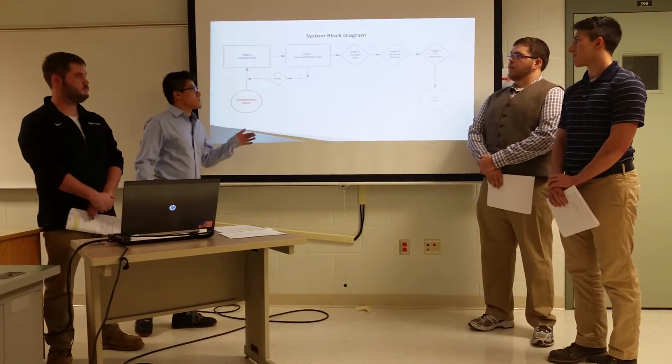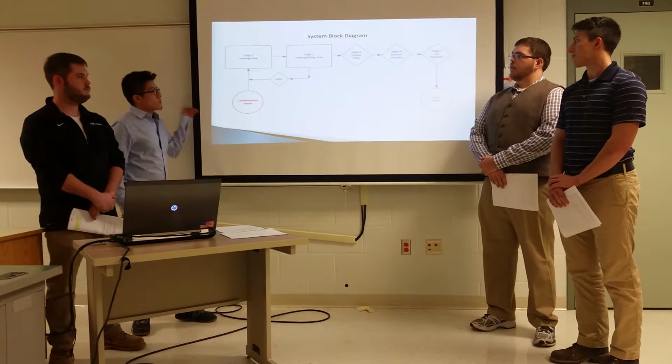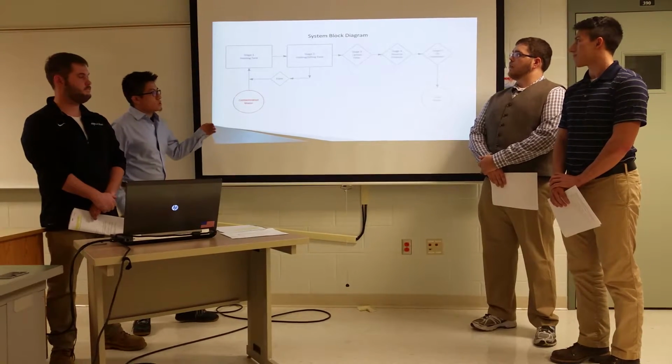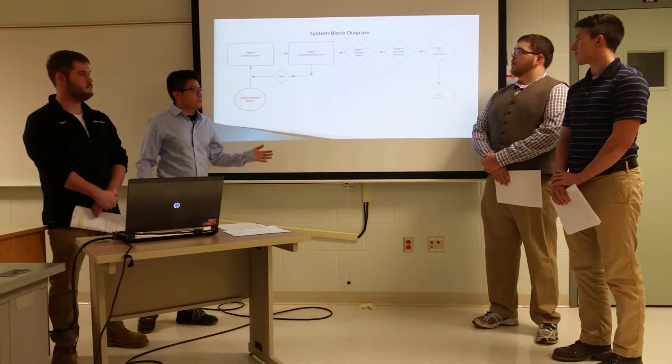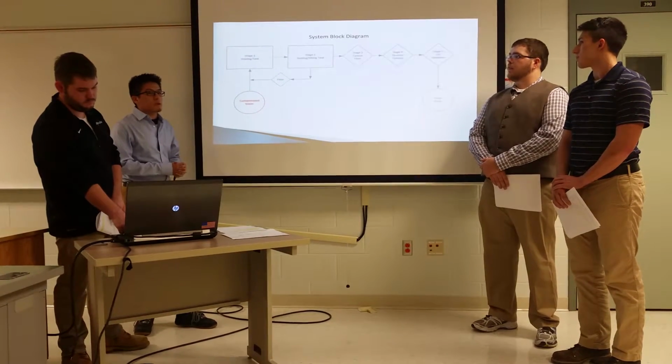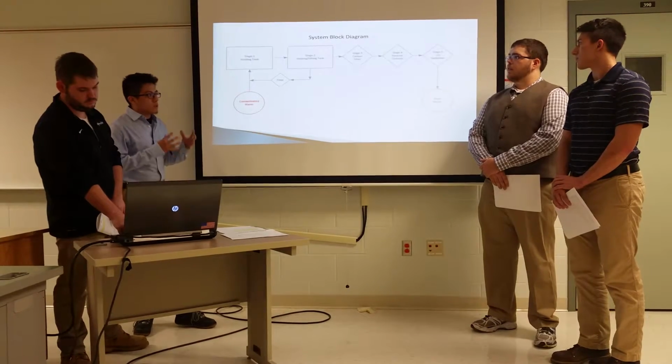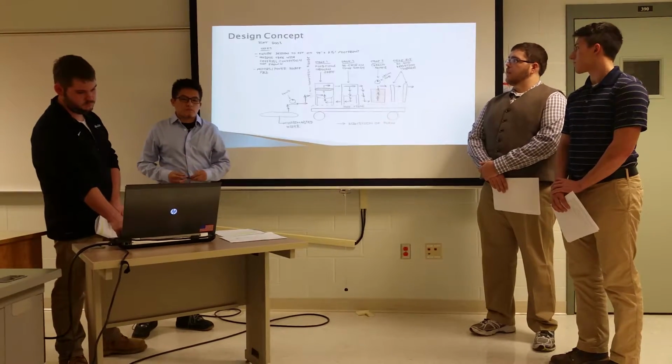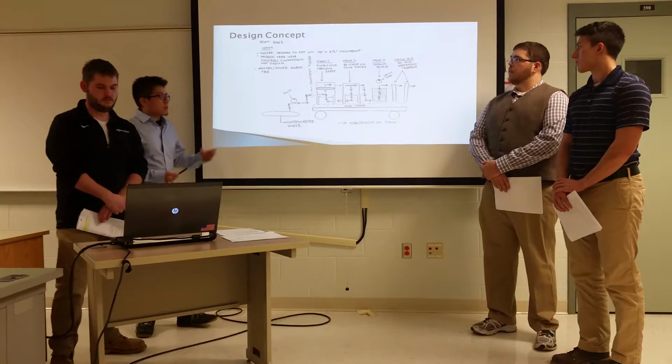We will be filtering the water through the stage. The fourth stage will have reverse osmosis. The fifth stage will have UV radiation, after which all of the water will be cleaned at a hopefully 98% efficiency. So this is our design concept.